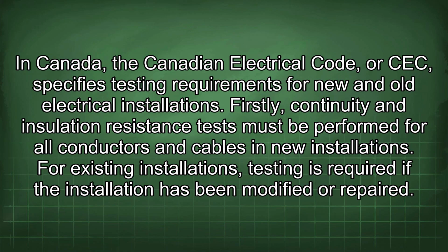In Canada, the Canadian Electrical Code, or CEC, specifies testing requirements for new and old electrical installations. Firstly, continuity and insulation resistance tests must be performed for all conductors and cables in new installations. For existing installations, testing is required if the installation has been modified or repaired.